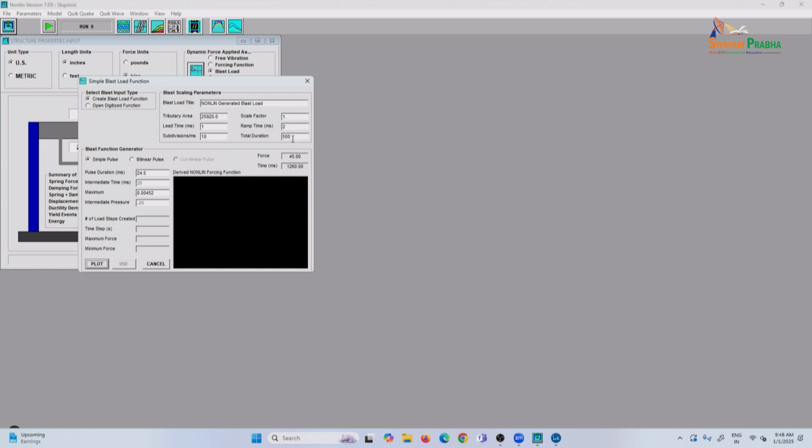If you want dynamic reactions as a function of time, there is a limitation. You can't change this for some reason; at least in my case I am not able to change subdivisions per millisecond. You start putting 5,000 milliseconds and then it is looking at 50,000 sub steps, and then it crashes. So, I was able to go up to 3,000, but for now I realized we do not really need all that. There is a way to do without it.